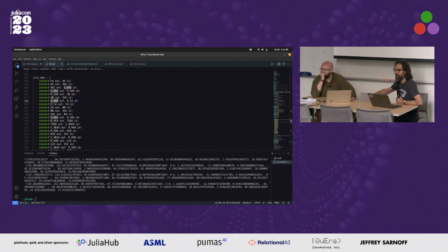So you don't need to go through that and rewrite your whole connect statements. Because you now have a branch that connects to multiple elements, you can just connect the element that you want to connect to the element you want to connect it to. And Modeling Toolkit, not our system, Modeling Toolkit will now figure that out for you. So that wasn't the case in the beginning, which made it a bit more tricky to get these connect statements in, but the new version of Modeling Toolkit since 8 point something is pretty clever in that. So whatever you do, it should give you a stable system in the end.